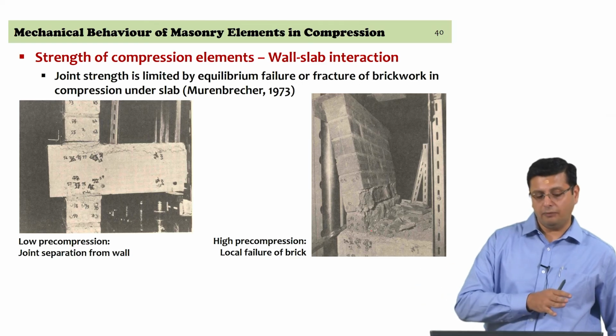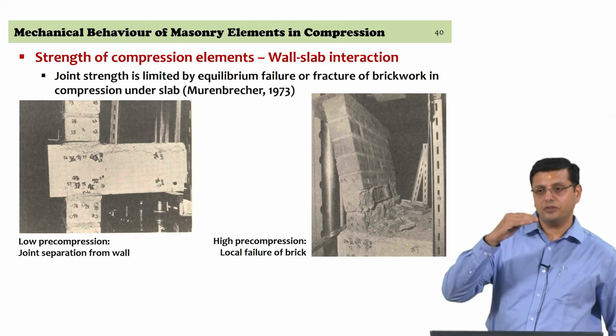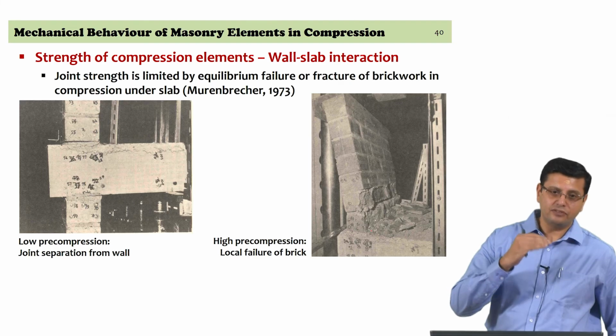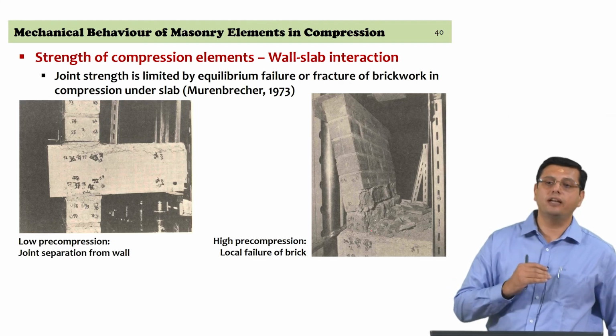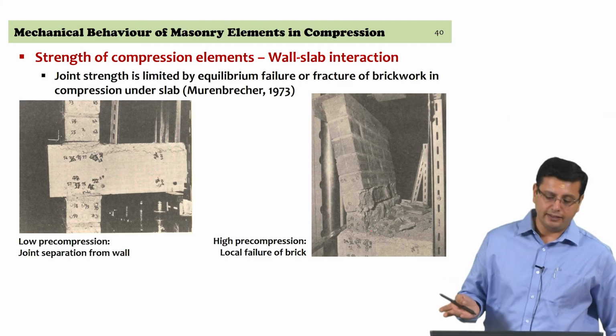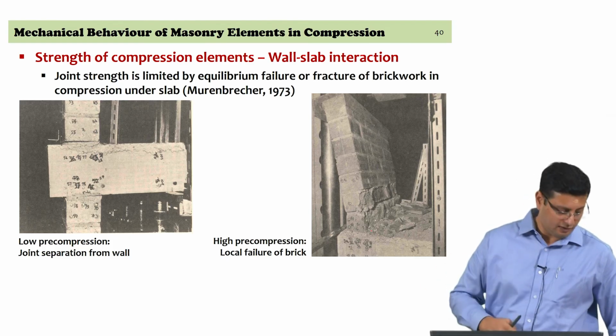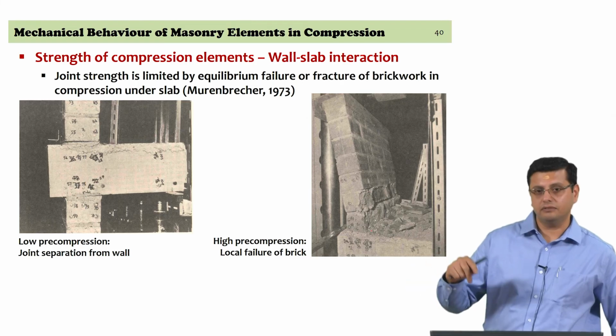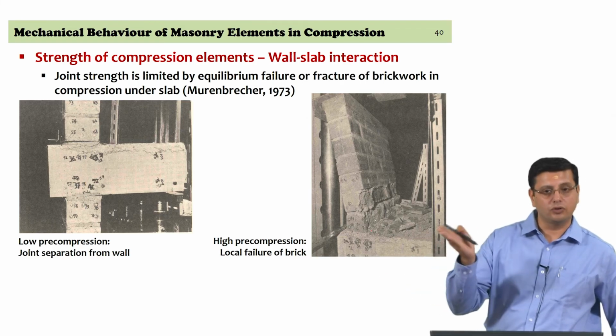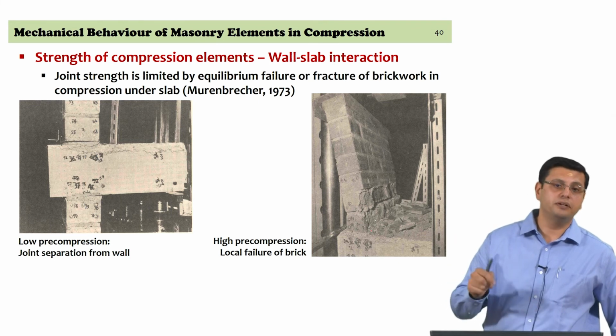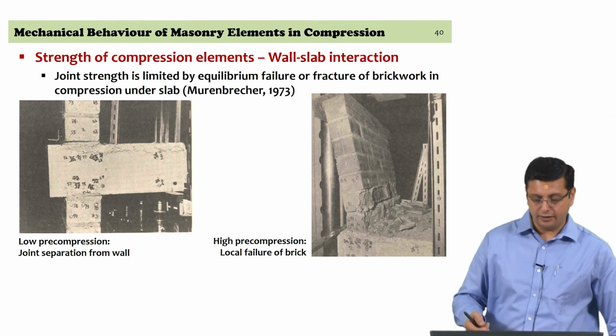So, the point is that interface will behave differently with respect to the level of pre-compression. It can either crack, or it can crack and rotate, or crush, and therefore, if it is crushing, then you have the non-linear behavior of the masonry wall. The rotations in the masonry wall will be different, and you cannot assume a linear response there.